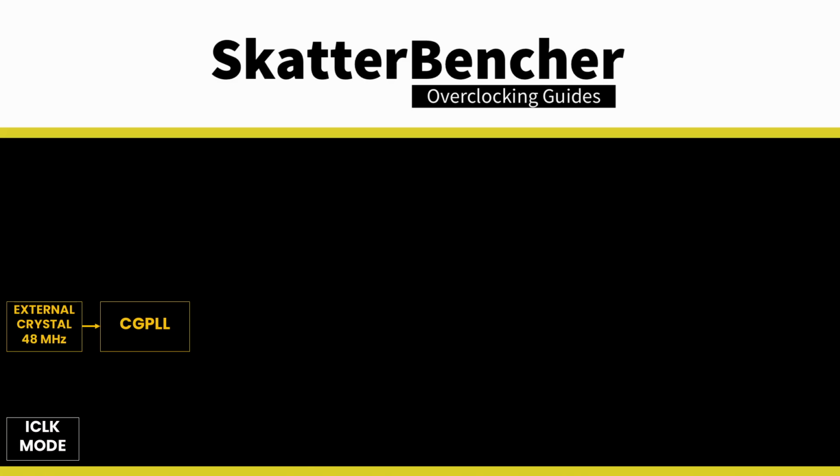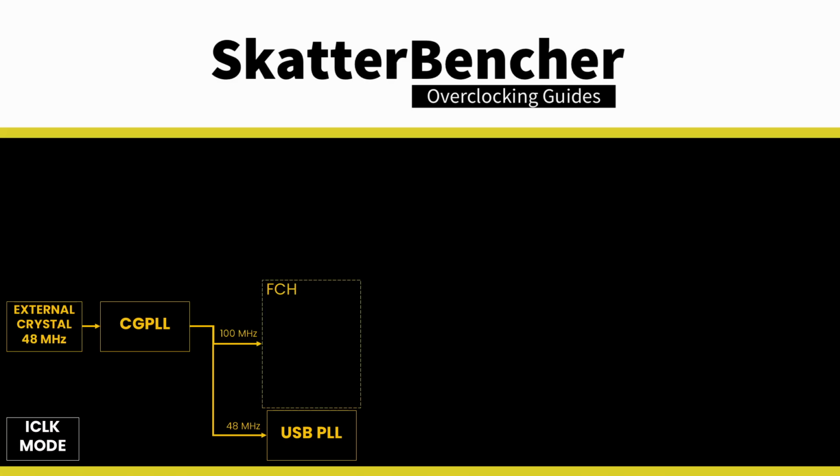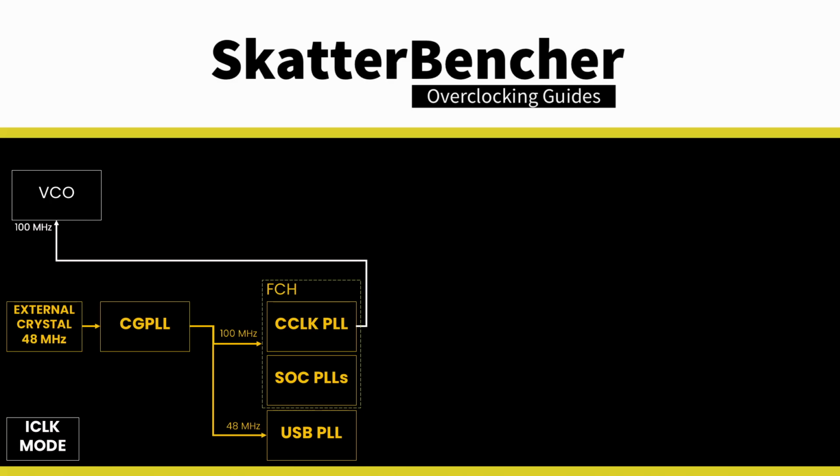The CGPLL then generates a 48 MHz clock for the USB PLL and a 100 MHz reference clock for the FCH, which contains the CCLK PLL for the CPU cores and several SLC PLLs. The CCLK PLL 100 MHz reference clock drives the 200 MHz VCO, which is then multiplied by an FID and divided by a DID. As a whole, this provides CPU clock frequency granularity of 25 MHz.